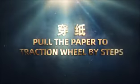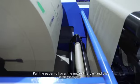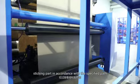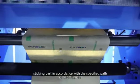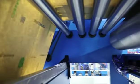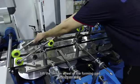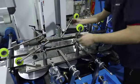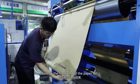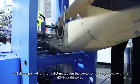Pull the paper to the traction wheel by steps. Close the tension. Pull the paper roll over the unwinding part and the sticking part in accordance with the specified path. Lift the friction wheel of the forming part. Before the paper roll goes into the forming part, fold up the front end of the paper roll. Pull the paper roll out for a distance.